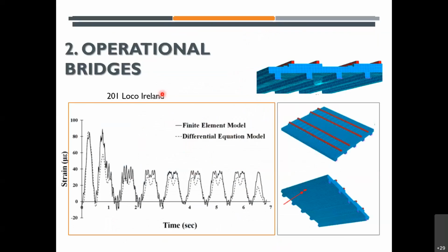And then we started moving these trains over a typical generic bridge made with finite element models, with rails and everything, with two trains passing each other, one train passing at various velocities. So, a complete parameter study, along with the damage induced as a local area that has a stiffness that has been degraded. Why? Because if your model isn't right, I mean, of course, the bridge doesn't know that you're modeling it, but unless you have a fairly reasonable model, it would be very hard to do anything.